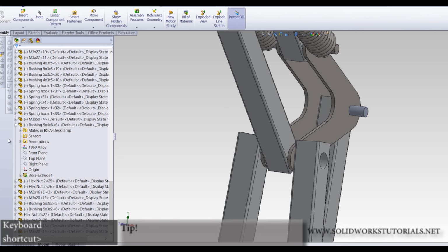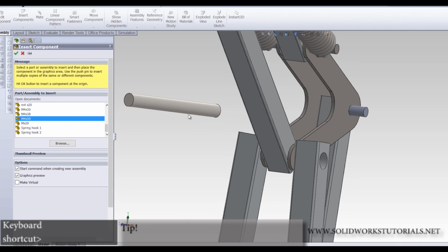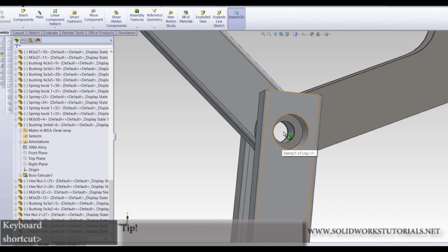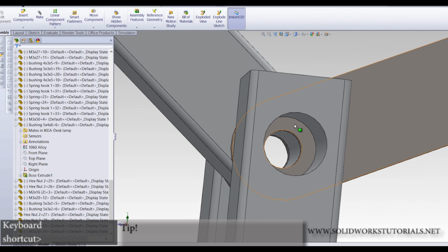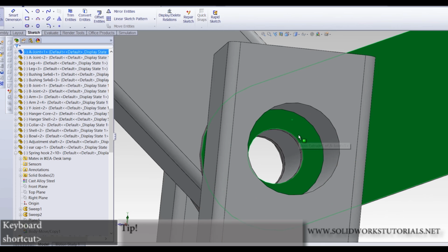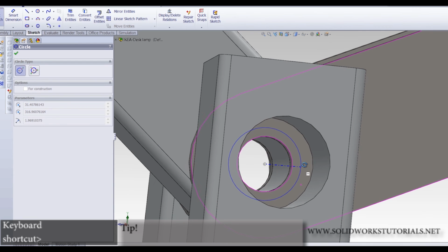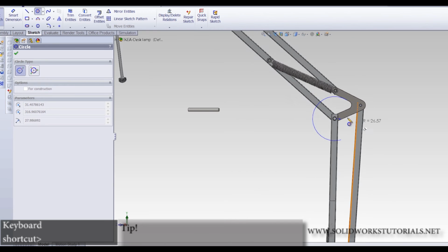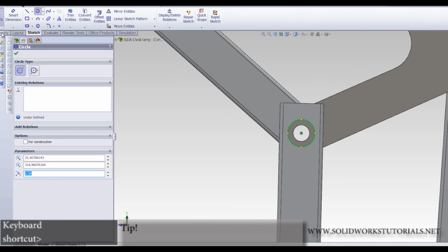Insert M4X50 now. Here we have it. Now I see the hole on my A joint, on the lower A joint, is 3 millimeters. So let's just fix it right here, right now. I'm going to click on it and activate sketch. I'm going to make this hole bigger. Draw a circle exactly 4 millimeters in diameter, or just place it on the edge of this hole, which is already 4, and go to the assembly section.